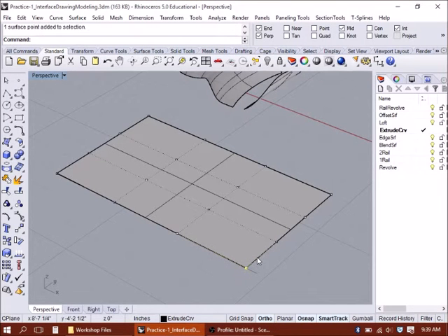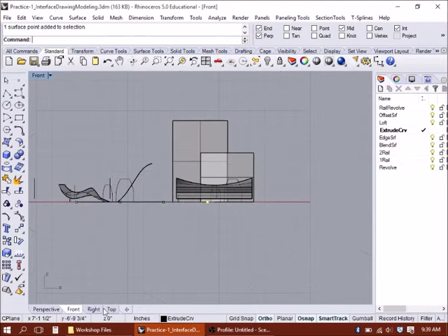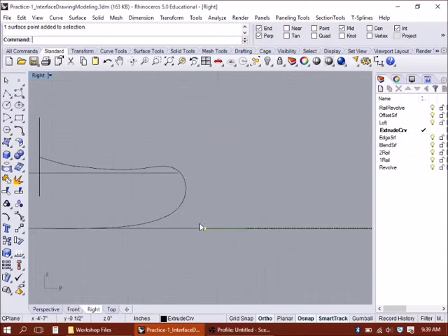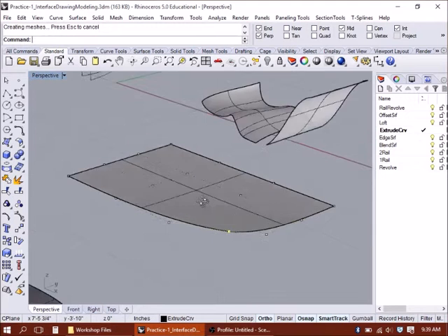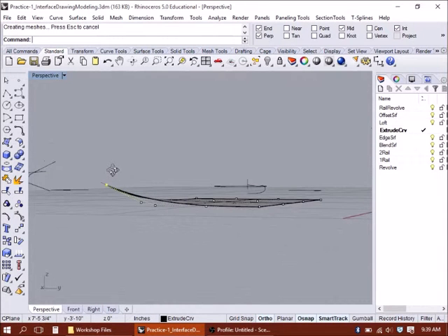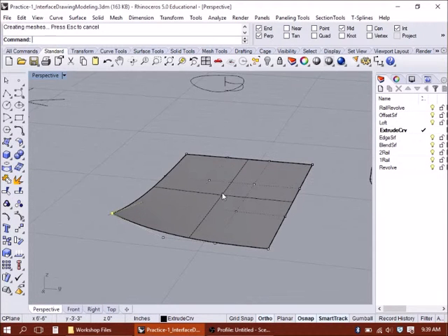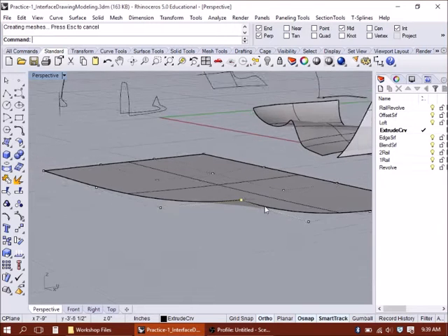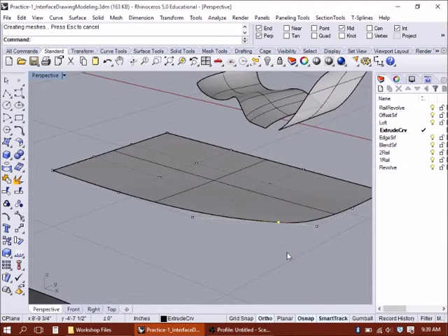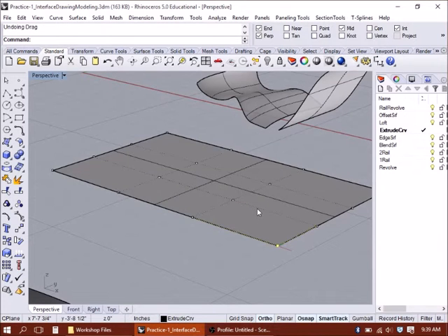And if I select that same corner and make that same change I did previously, see, it's behaving quite differently, right? And so it's taking into account all these other control points, and now it's much more gentle of a manipulation that we're seeing there. So that's a combination of working with the degree and the control points.